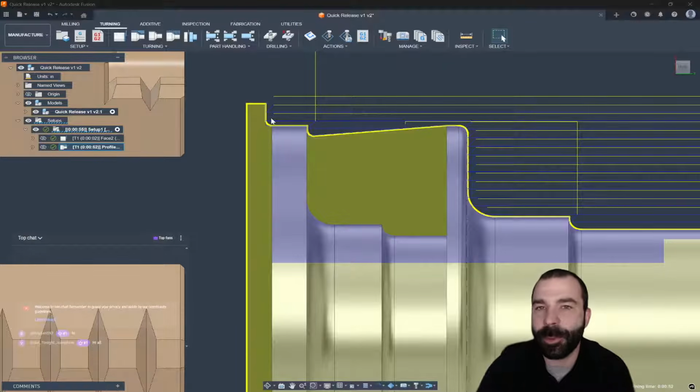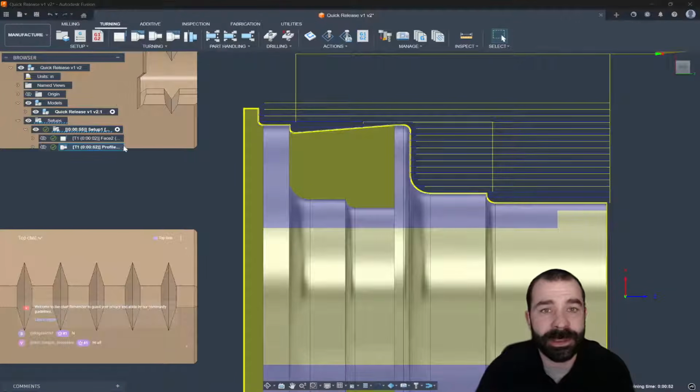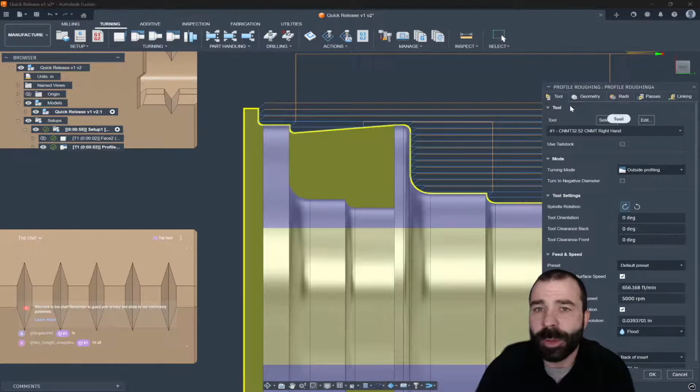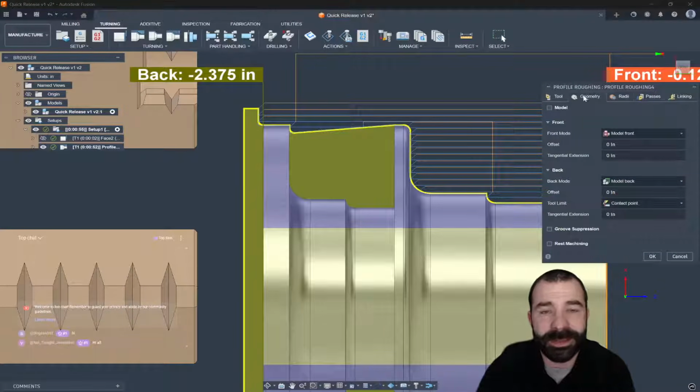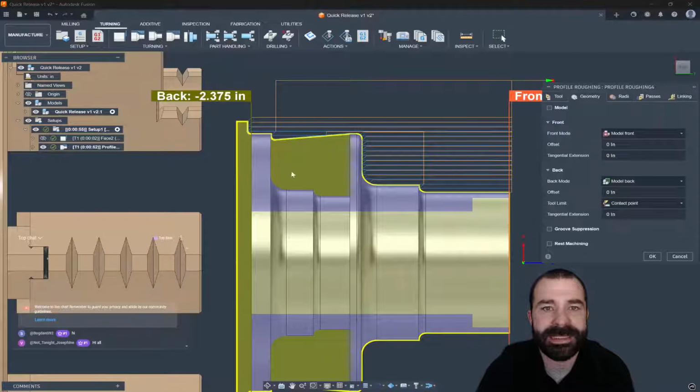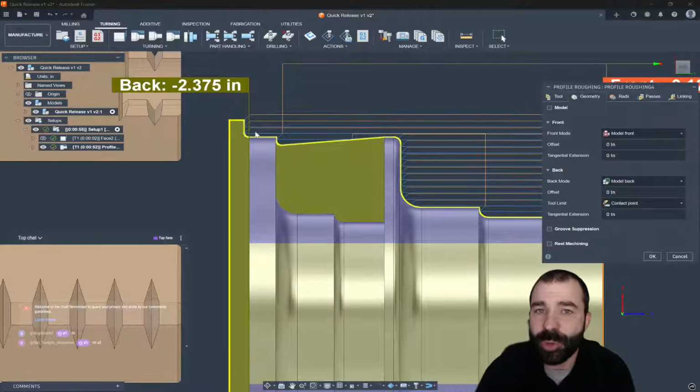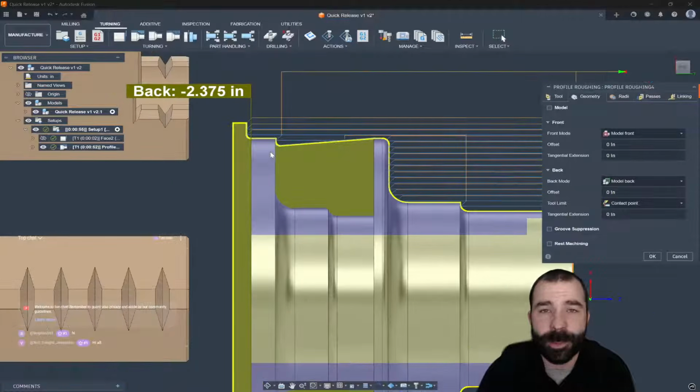This is very important because as we teach over here at Lathe CAM, we're always going to want to walk through our tabs left to right, right? So we want to make sure that our geometry in the Z-axis is defined properly. For some of you, you may be parting off this file, right? So again, we want to part this off when we're done with all of our OD turning, which means we probably want to turn this further back.